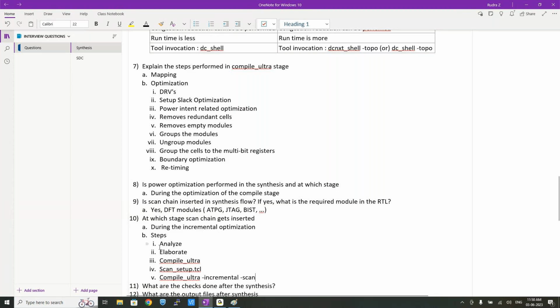After the first three steps, you will have one gate level netlist. And after the second step, we will have another gate level netlist, to make sure that this scan insertion is not disturbing any functional connections. To verify that, we extract different netlists. Okay, clear? Any questions, any doubts?